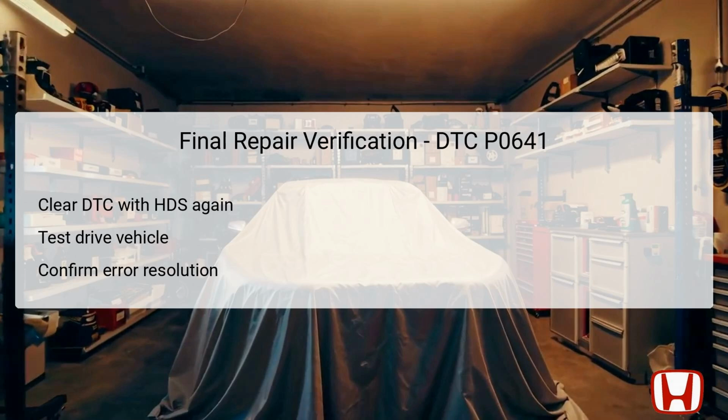During this drive, monitor vehicle performance for any signs of hesitation or engine issues that could indicate incomplete repairs. It's vital to ensure that all sensors are working correctly and that the expected voltage levels are achieved. If the DTC does not reappear, it confirms the resolution of the underlying issue, ensuring optimal vehicle functioning.